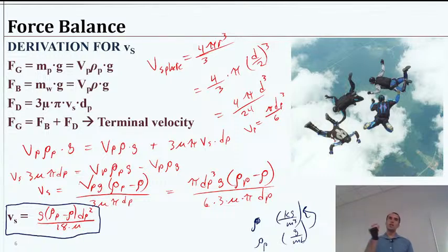So making them bigger particles will inherently make our stuff settle faster, because that's on the numerator here to the square power. We'll come back to that, but just giving you a little foresight into how we are designing this, how we are helping our designs. Most of it's going to be manipulating that particle size. And typically, the way we'll do that is try to get particles to stick together to form larger particles.